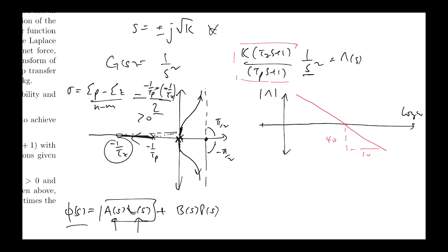This guy, by virtue of the relative position of the pole and 0, the pole's going to kick down at a particular frequency, and then the 0 is going to kick in to flatten it off again, right? So we're going to end up with something that in total does this, and then it goes down, and then it'll run parallel, okay? And changing the location of the pole and the 0 just changes where this kicks down and where this flattens off again, and they'll move around to the left and the right depending on how we move these to the left and the right. All right?